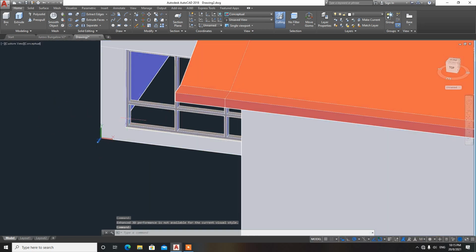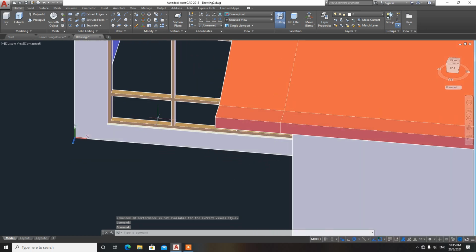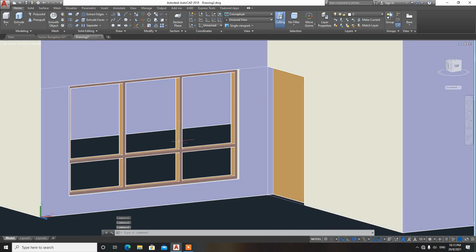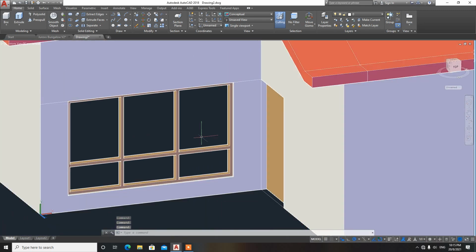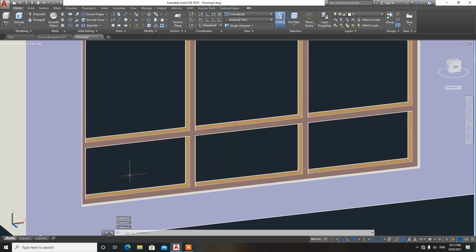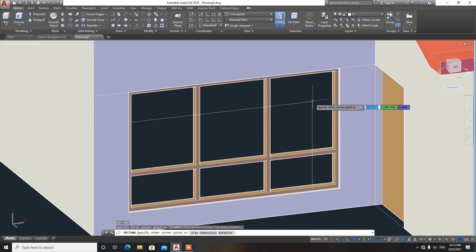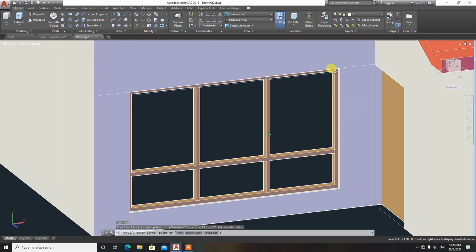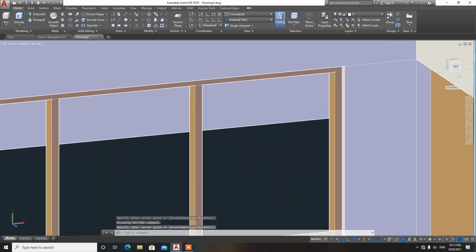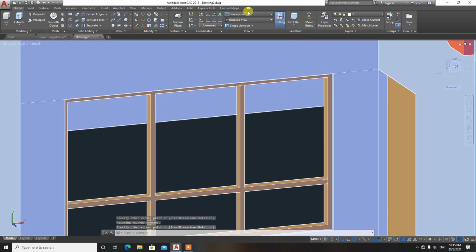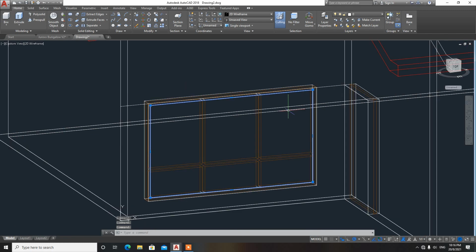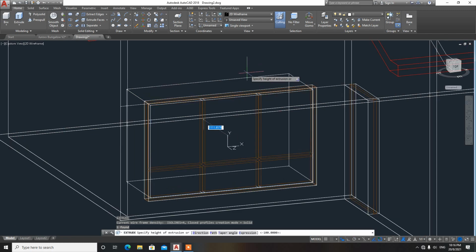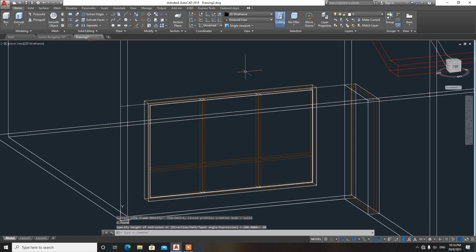And we can draw the glass also there. I will draw a rectangle here. Just type REC, enter, starting from here, and orbit this a little bit until I reach here. So I got that already, and then I'm going to change to wireframe. I got this part. This is my glass. I'm going to extrude it a little bit, maybe around 20.